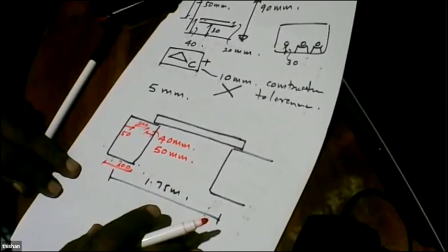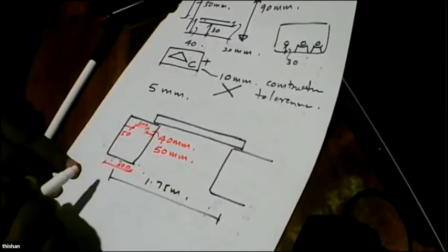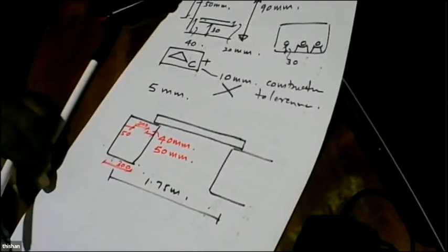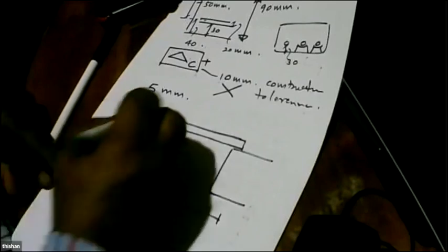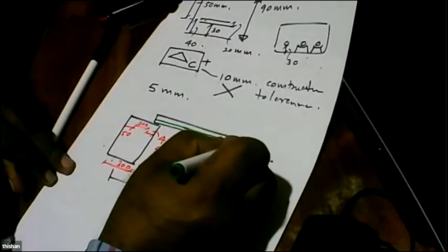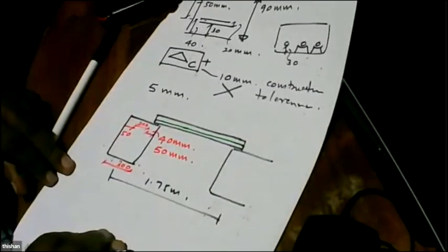The reason is we have to make sure these precast members are kept. But the most important thing about these precast members is to make sure when you are precasting, the reinforcement continues from this to this, end to end.